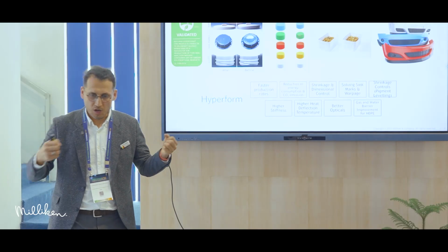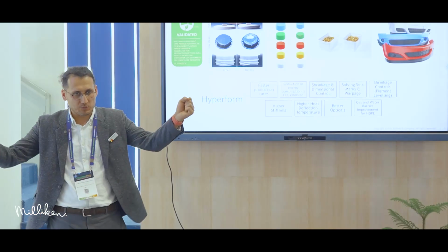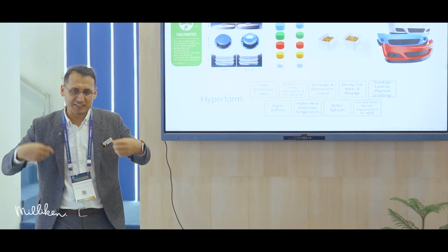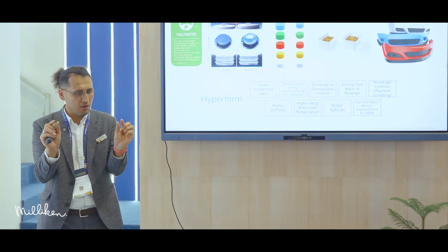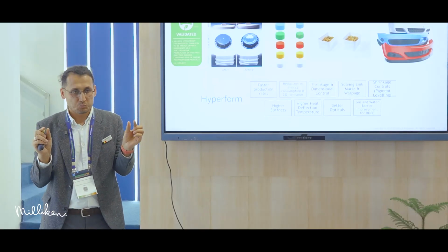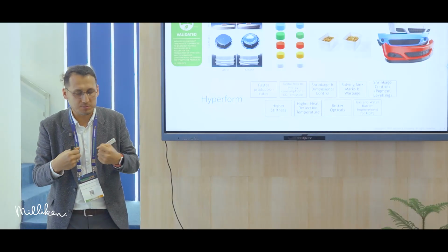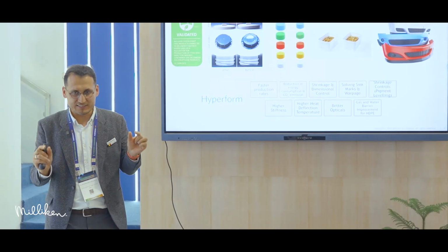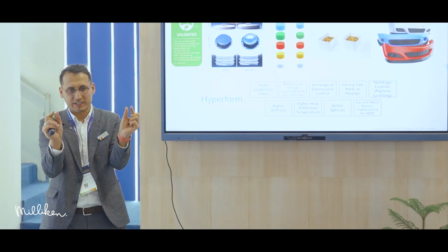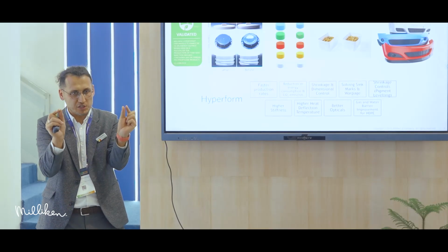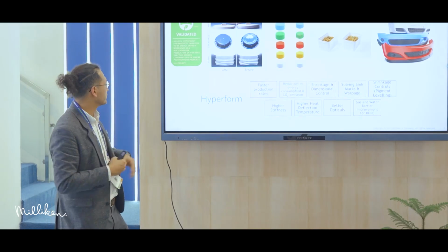the car goes to a hotter or colder environment. You don't want the bumper to expand or shrink too much. But because PP in general, in nature, will expand and shrink, car makers always put a small gap between bumper and another part. Otherwise, if it starts to expand, you'll start to fight each other. It will have problem. So if you have a better CLTE for the premium car, they don't like that gap. It looks ugly and it's not good aerodynamic. So if you have a good CLTE, they can reduce that gap. So this is also the application why nucleator is helpful in automotive.